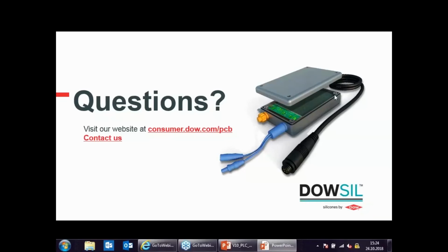Okay, next question. Other than OEM requirements, why should we apply conformal coating to PCB? Just to have a better reliability of your PCB, to reduce the short circuit issues, to improve against any mechanical or also chemical ingress if your application is in that case.